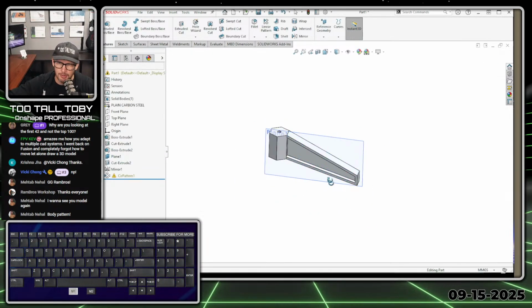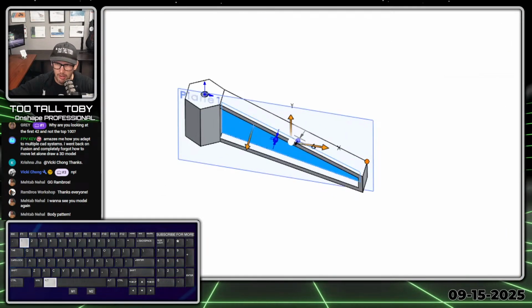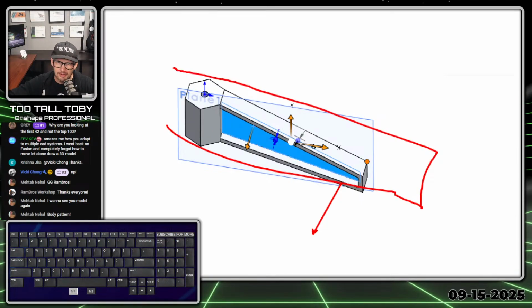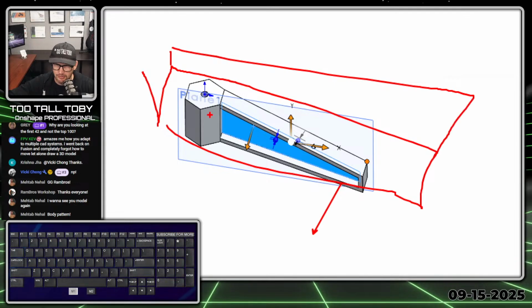could be happening here is when you do a cut extrude through all, the end condition is dynamic, and sometimes it's a hard time solving that end condition, because what through all means is look at the boundary of the part. So the part has a bounding box. You can imagine this part has a bounding box here. Look at the boundary of that box and then extrude cut until you come to the furthest point on that bounding box. And that's where you're going to stop it.